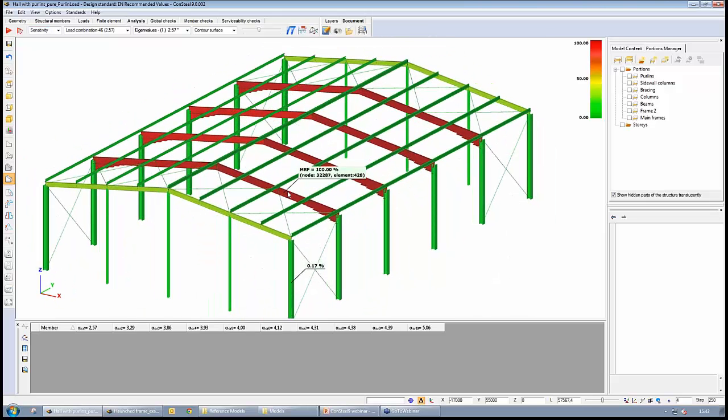Of course, when we see the buckling form, sometimes it is evident which are the dominant members, but this sensitivity analysis is a mechanical tool to evaluate the critical member based on the buckling mode and the calculated internal energy in these buckling modes. So we can see that the dominant critical members are the beams.